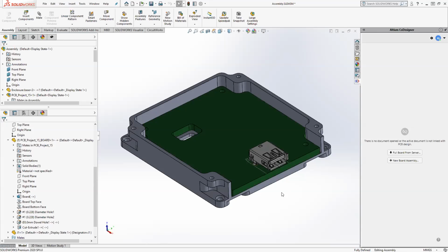What will happen is if any changes are made in Altium, when those changes are pushed to MCAD, the board outline, instead of just being modified in MCAD, will actually be deleted and rebuilt from scratch, which means all the internal edge IDs in MCAD will change, and all of the constraints that relied on those edge IDs will be broken. So it's just something to bear in mind for your workflows.